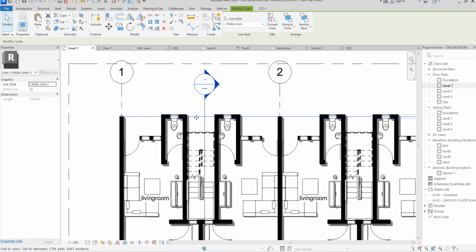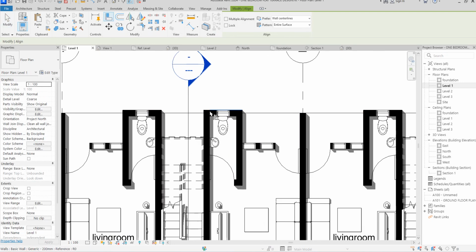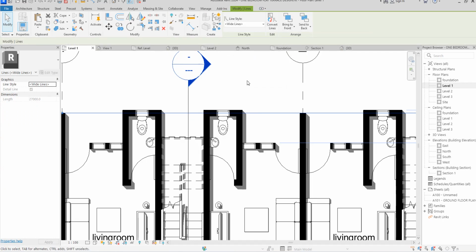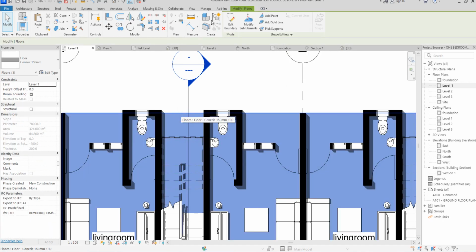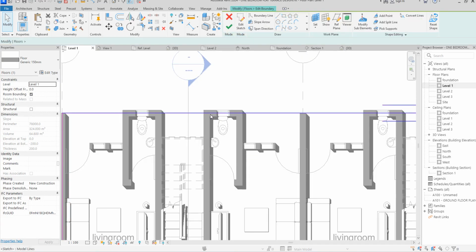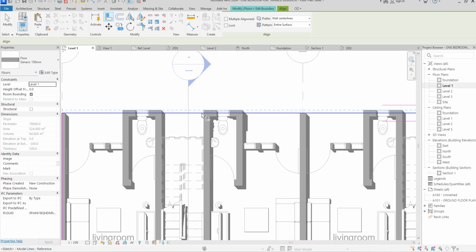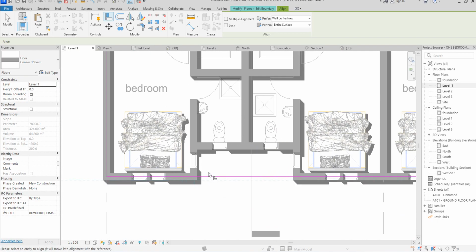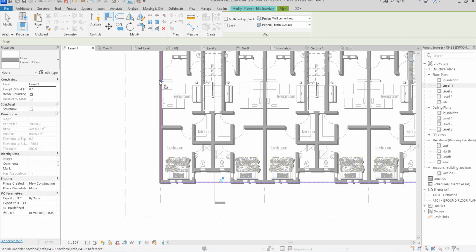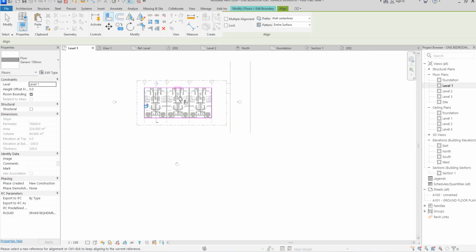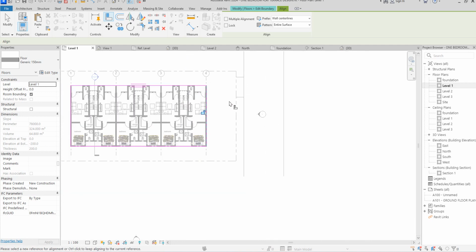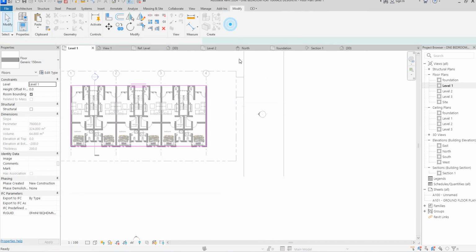So what does it mean that we are climbing to get to this position? This one is a normal ground floor. So I'm going to edit that and align it to what needs to be aligned here. Sorry, I've not edited this, so I was doing the wrong thing. This is the white line, edit the white line. So I'm going to edit the boundary now. So I'll align, then align. It's as simple as ABC. Align the external wall as well. Align. So finish and you click finish.